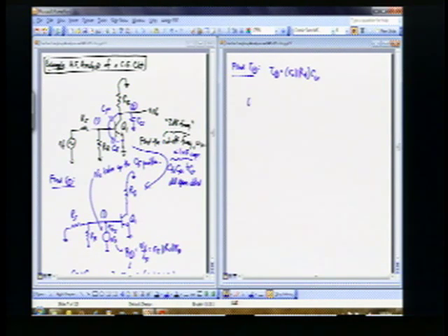And now I can just write as a solution for this that the high frequency cutoff, if we have a dominant pole, is just the sum of all of these time constants, which we have equations for, and 1 over that. So that now becomes my high frequency cutoff.